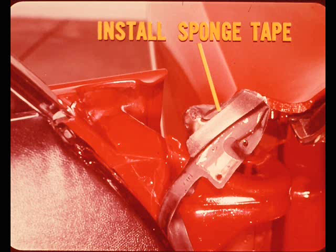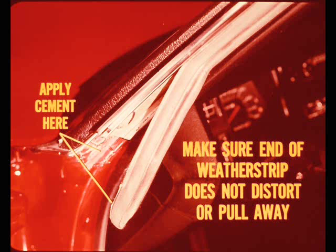Now, in some cars, a wind noise can result from a gap under the molded ends of the door weather strip. The best solution here is to install a strip of closed cell sponge seal tape between the weather strip and the door surface. When you check door and window sealing, make sure the end of the weather strip does not distort or pull away as the door closes. Cementing the weather strip end may be all that's needed.